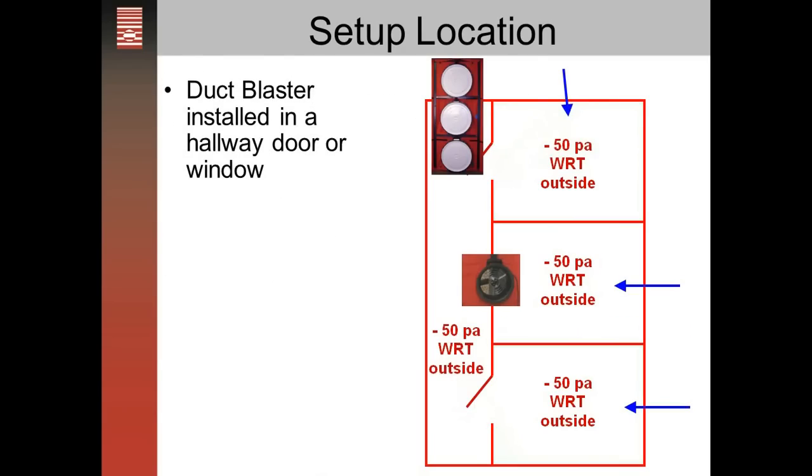Another option is to depressurize the whole building with multiple blower doors, open all the doors to all of the units, and so the whole building is at one pressure, and you can get one number on what the total building is to the outside.